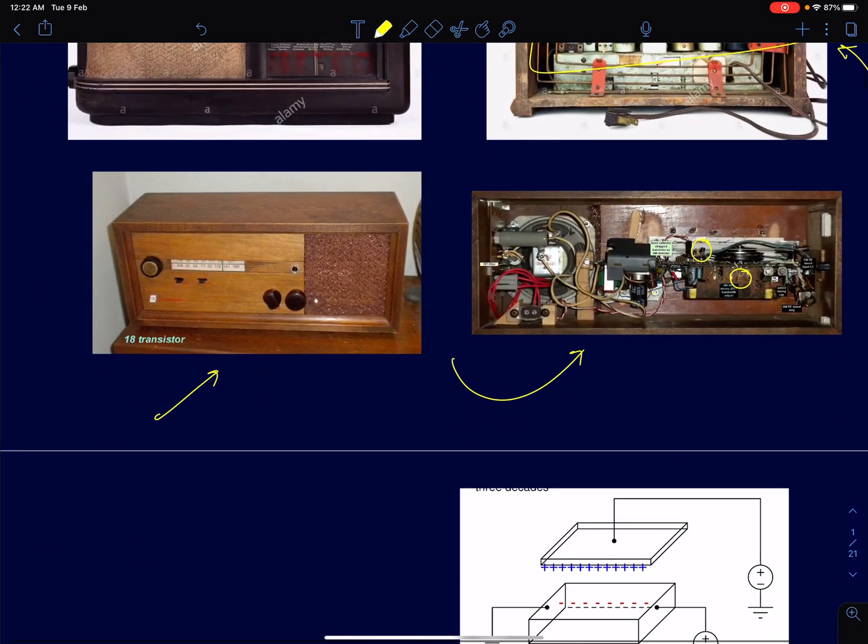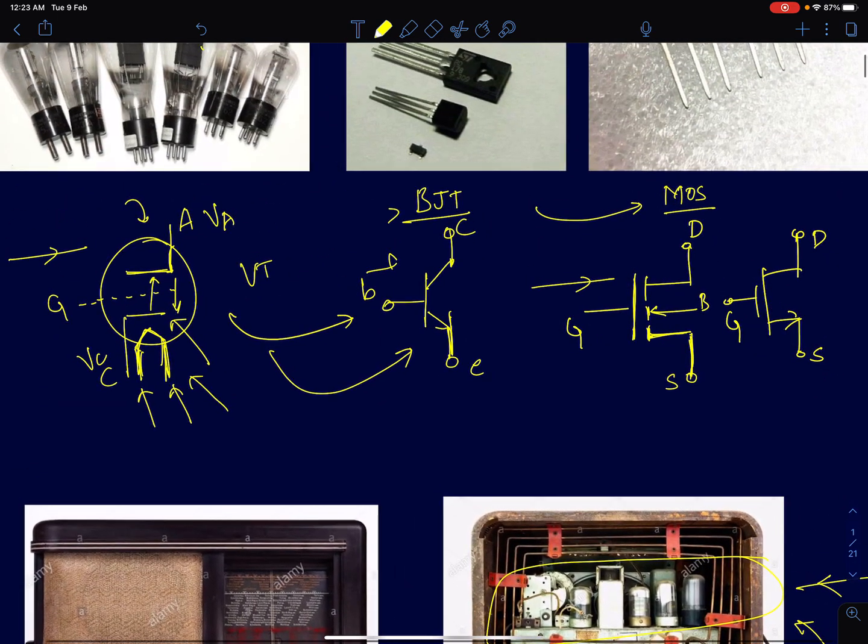Now, the shift from bipolar junctions to MOSFET is not as obvious as the shift from vacuum tube amplifiers to BJTs. Because a bipolar junction transistor, as we will see when we compare BJT and MOSFET, is a superior device as far as its analog performance is concerned. Meaning bipolar junction transistors can operate at higher frequencies than MOSFETs. They also give, for a given current, a higher transconductance than MOS amplifiers. But the invention of the bipolar junction transistor actually began with the idea of a MOSFET.